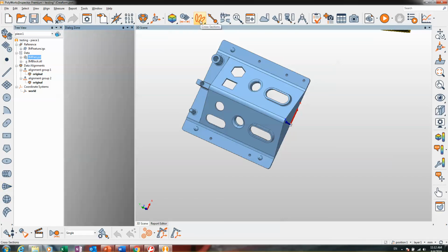Next is a cross section. This one is for cutting the part in the 2D view. This icon is comparison point. Comparison point, many methods. The common one is the surface. Second one is the trim line or trim edge. Comparison point on the cross section. This one is on the hem. When you hem the part, you just check the comparison point.